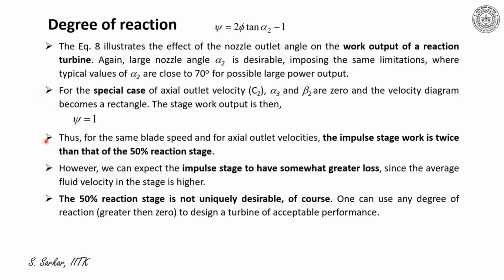Thus, for the same blade speed and for axial outlet velocity, the impulse stage work is twice that of the 50% reaction stage.